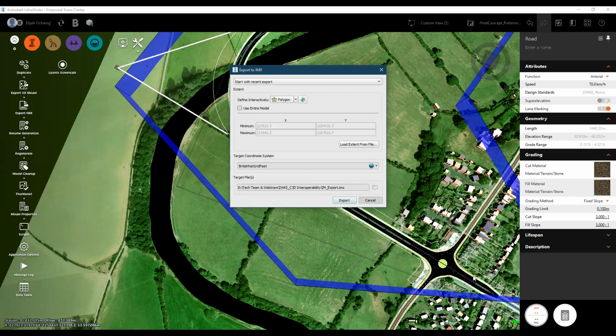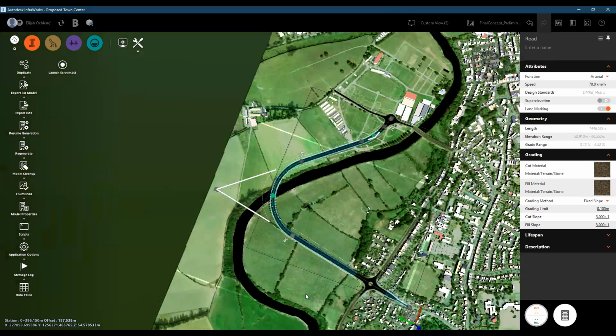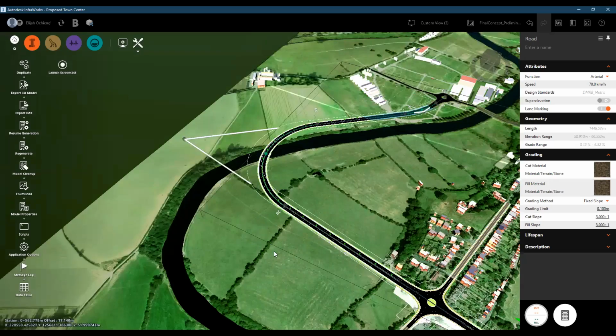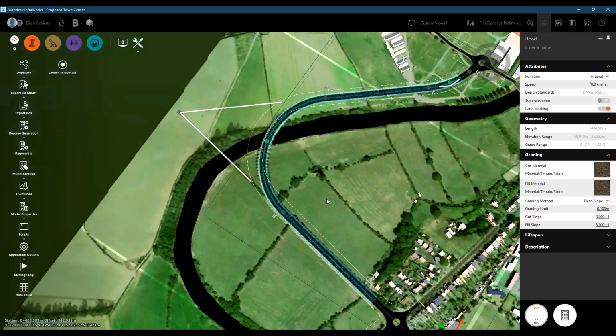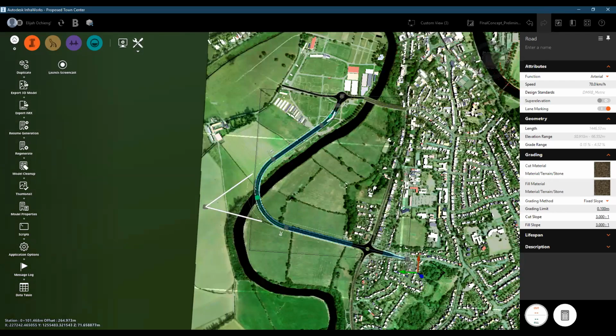Then I will move into Civil 3D to illustrate how we bring that concept in, where you'll be able to see that the process of importing your point files and generating your surfaces will automatically be done when you integrate Civil 3D and Infraworks. The surfaces that you created, both the proposed corridor surface and the existing topo surface, will automatically be imported, plus the corresponding road, corridor, and furniture will automatically be taken into Civil 3D during that process of interoperating between Civil 3D and Infraworks.